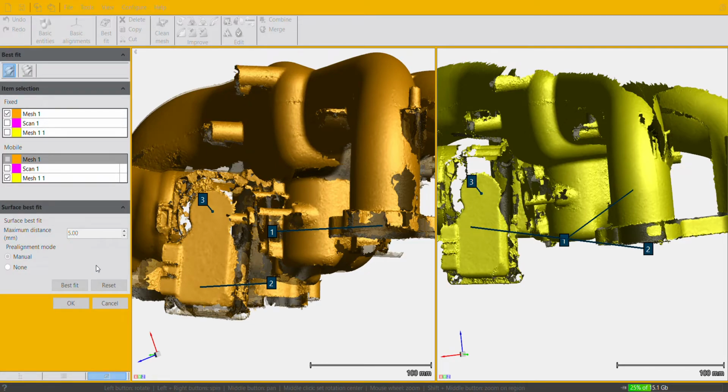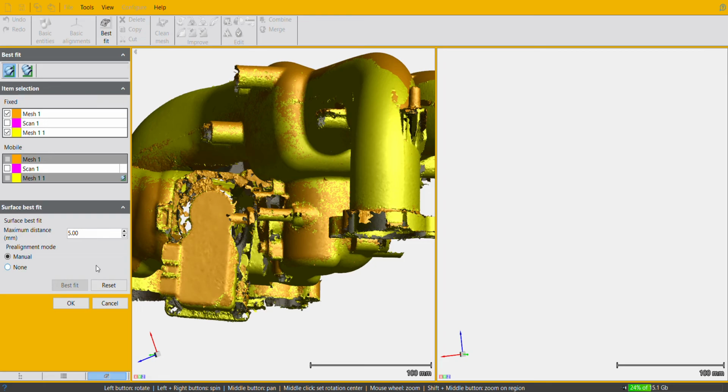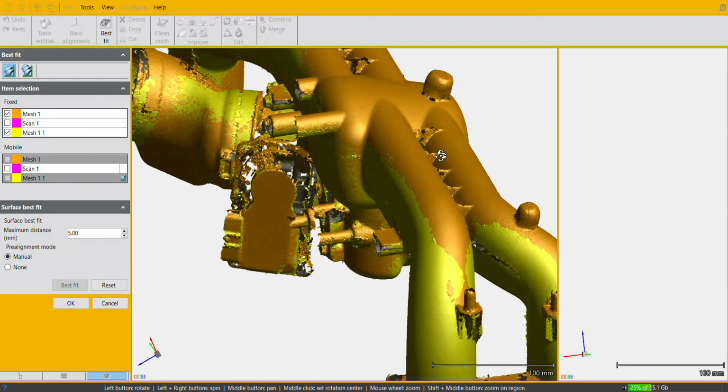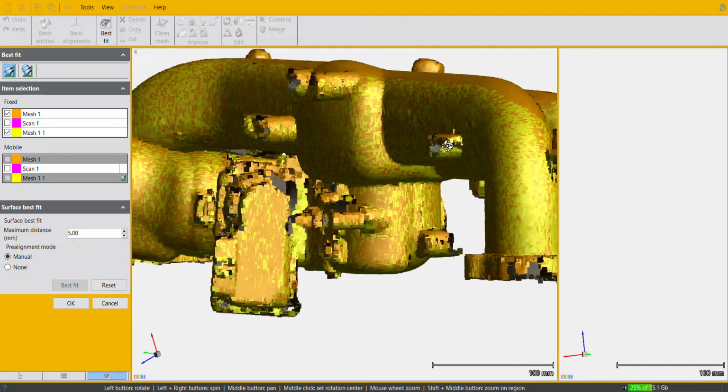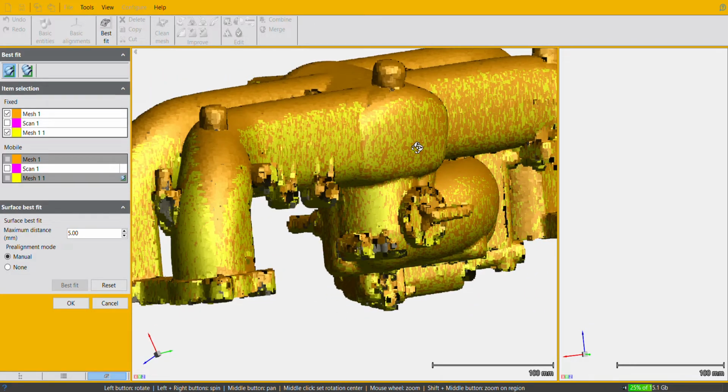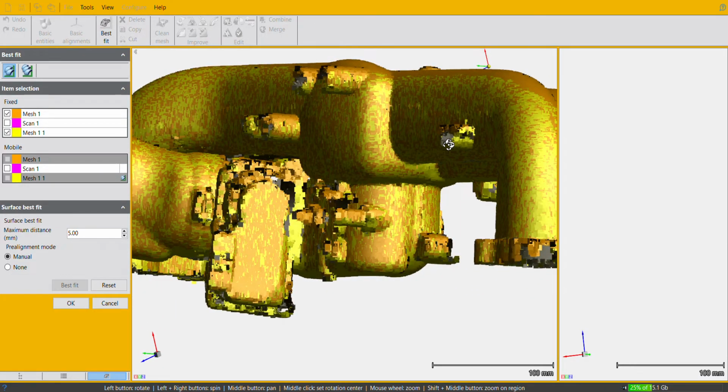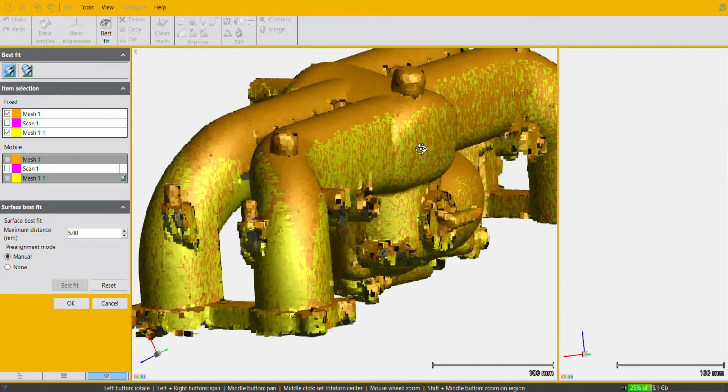You'll click it, and it'll give you a preview. You can still cancel from this point. You can reset and grab 3 points in case your scan looks funny. One of the things I do to check the scan real quick is rotate it around, and you'll see how it gets that tiger striped look to it. That's where it's overlapping meshes. So you can see front and back I have it, which means that the meshes are essentially line on line.